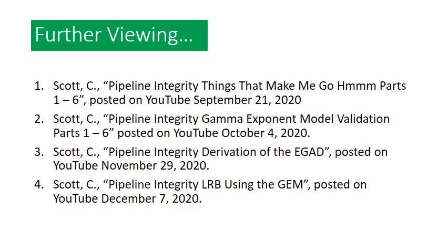For anybody that's interested in further pipeline integrity videos, I do have a series of videos on YouTube that you can find fairly easily. Probably the most interesting one for some of you will be Pipeline Integrity, Things That Make Me Go Hmm, parts 1 to 6. Those are really a critique of the original NG-18 Battelle work that was done in the late 1960s and early 70s. I think that back then the group made a couple of bad assumptions regarding the way length and depth are handled, and I think that industry should have a good hard look at that situation and see what can be done to resolve it, as well as looking at the derivation of my GEM model, which I think solves some of the theoretical problems from 50 years ago.